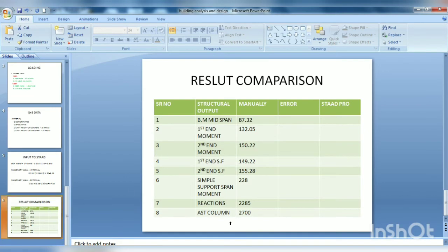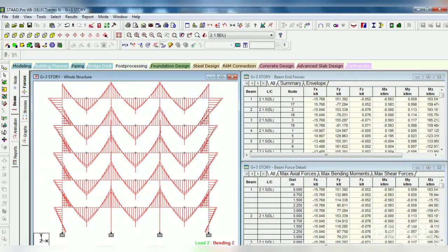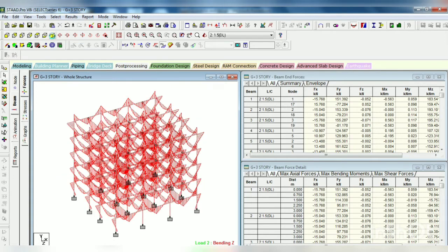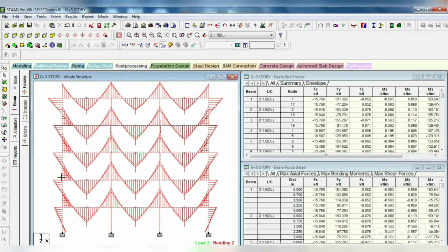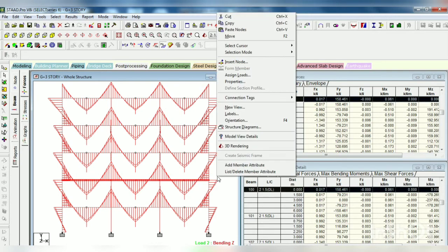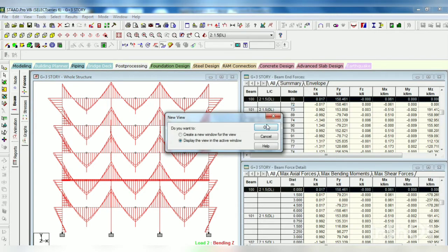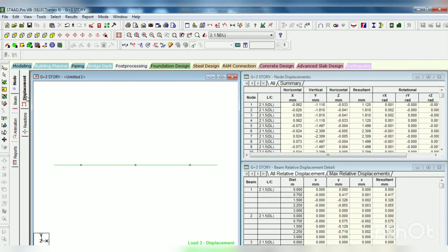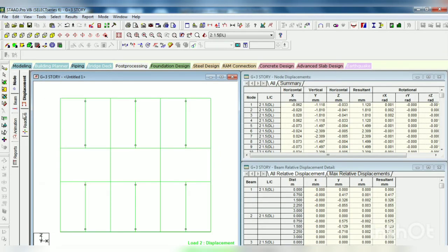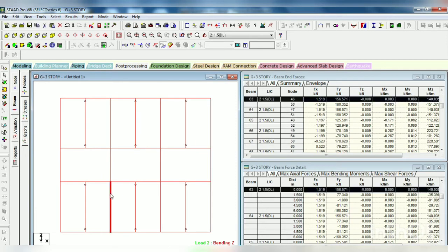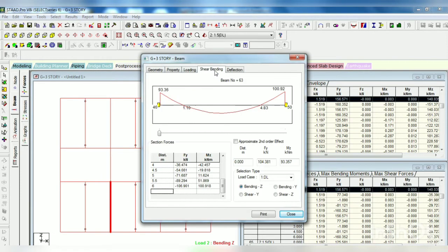Yes, here are our results that we have calculated manually. You can check the videos. You can click on the I button, or you can go to the playlist of designing building manually. Now select this floor, because on this floor I have done the analysis of the beam. So go to the top view and go to the beam. Yes, these particular beams I have analyzed. Yes, select the combination case, and now you can see the support moments at 140 and 151.